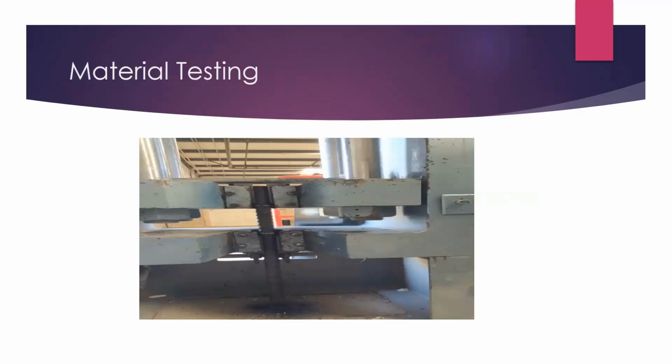And the size of the bar is measured in 1/8 of inches. So if you have a number 8 bar, that means it's 8/8 of an inch, which is 1 inch. So if you have a number 11 bar, I believe that would be 11/8 of an inch, so a little bit higher than an inch. All right, so this is the video. Let's watch this. Oh, I gotta get my clicker.